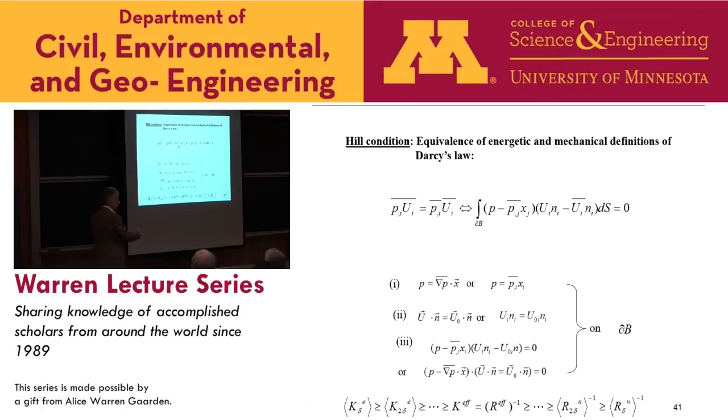Whereas in other problems in elasticity, we have gradient of displacement, which is strain, and then traction. So the roles kind of are interchanged now. So I have a Dirichlet problem, which is then controlled by mean pressure gradient, mathematically corresponds to like mean strain, and velocity boundary value problem here.